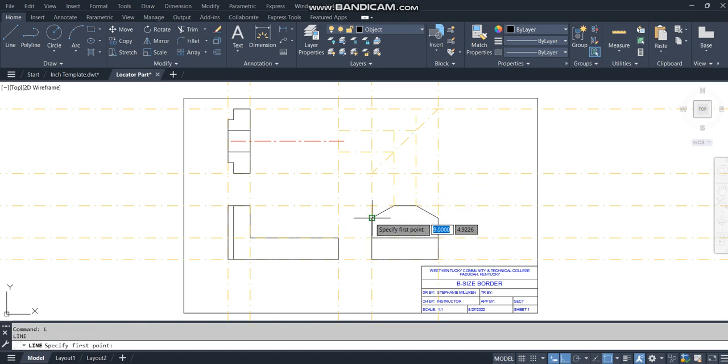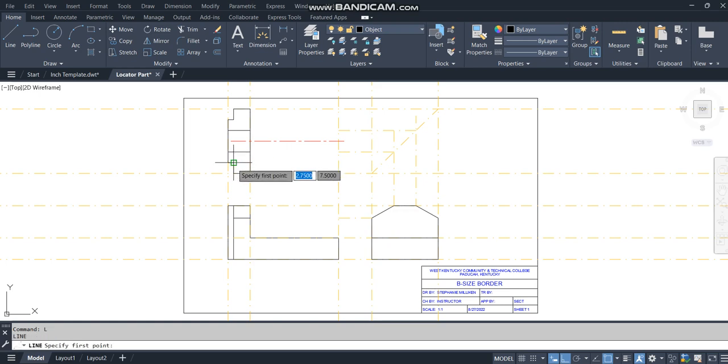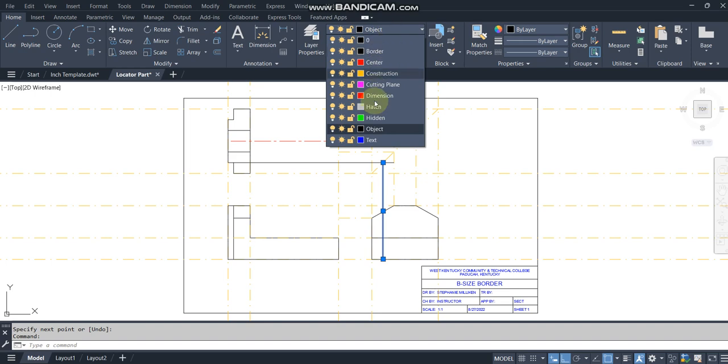Now I have where this comes over and hits at the side view. And again, trim that out. If you want to leave it as a construction line, you can leave that. When I get to the end of this, I will turn all those construction lines off so you can't see them anymore. Now if I were looking for where this cut is located, I would project it from the top view down to my side view. And since this is the side and that cut is on the back, this actually will become a hidden line.